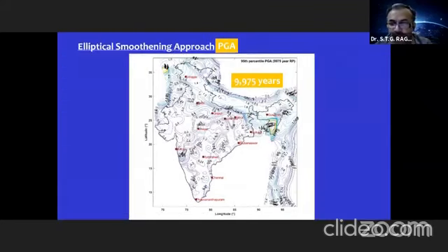And of course, the design value will be very high, but the risk level will be very small actually. So you can see the values are 2 G, 1.7 G. Now you can compare these maps with the United States maps, which I showed in the starting. Our numbers are also more or less similar to the other countries' numbers. And now this is for pseudo spectral acceleration at 0.2 seconds.